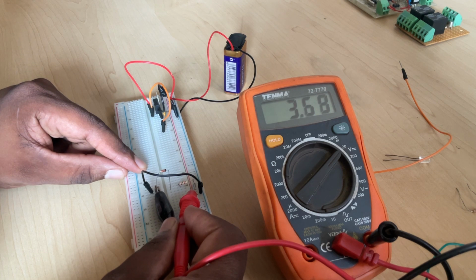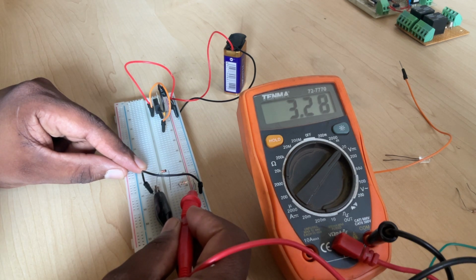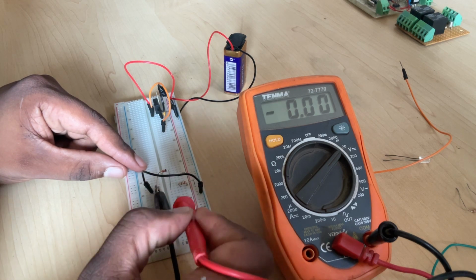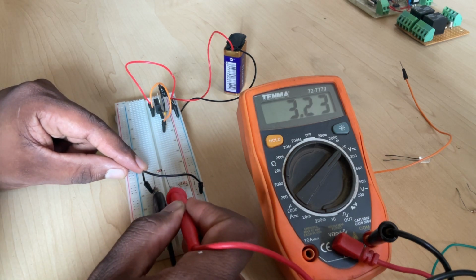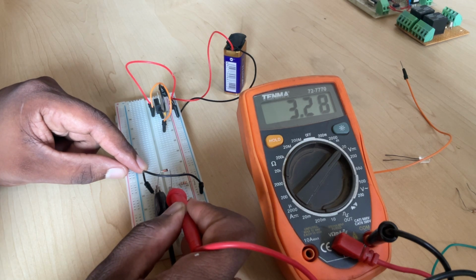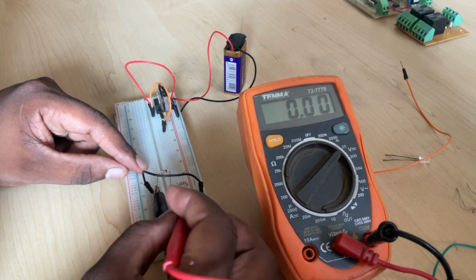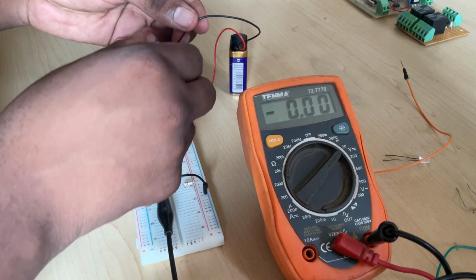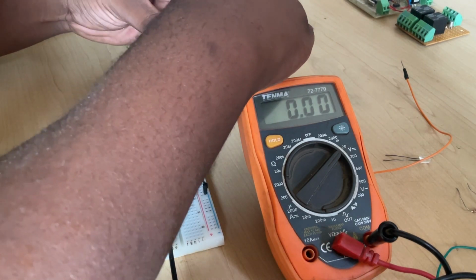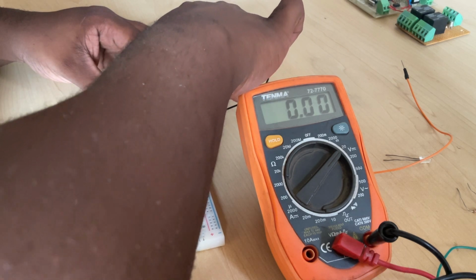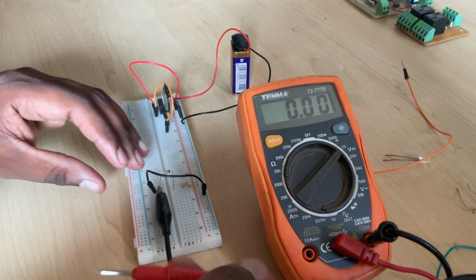With the first measurement, something seems to be out of place. This voltage does not make sense given the power supply that we have. So this calls for some troubleshooting. And here I easily found that the battery was not properly connected, or it got disconnected when I moved the breadboard. Placing the connection back in, we can check.